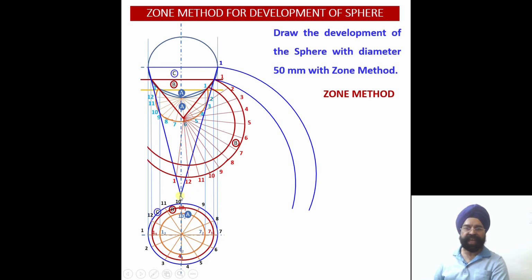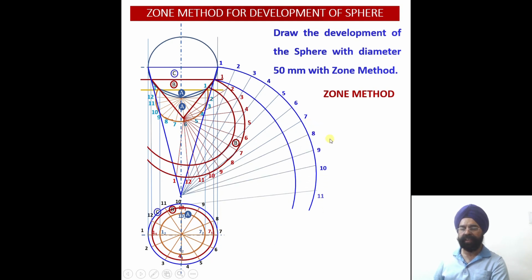So starting with this as my radius, that is the apex point, I am going to draw multiple arcs. From here, I am going to join all of them radially thereafter. First arc I will be drawing from 1 over here, join it radially. Again, you cut the second arc from 2 to 3, again join it radially. Again cut the fourth arc from the third point, and this way keep on cutting 12 arcs. So fifth arc, sixth arc which has been joined radially, 7th, 8th, 9th, 10th, 11th, 12th, and again get back to 1.